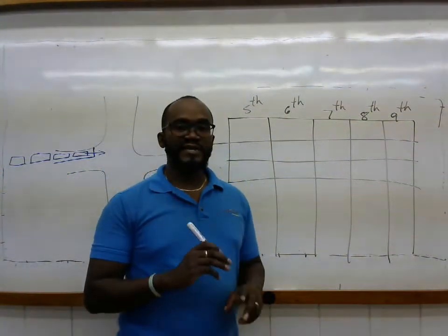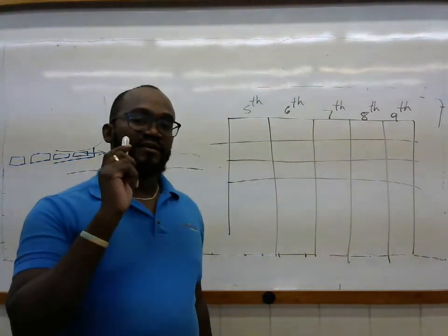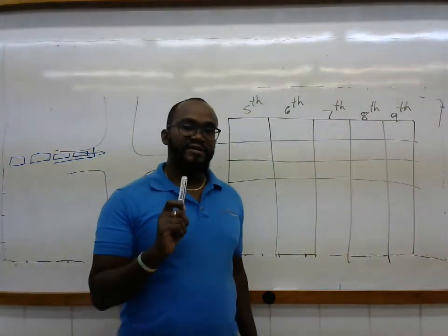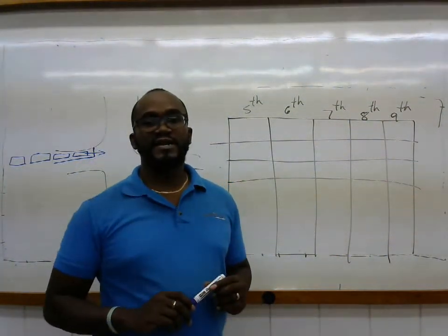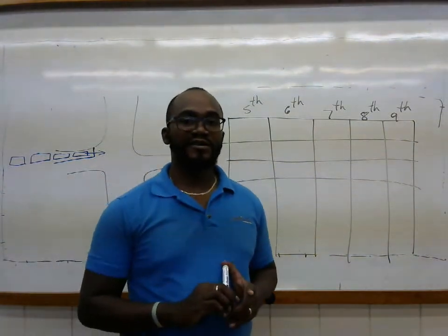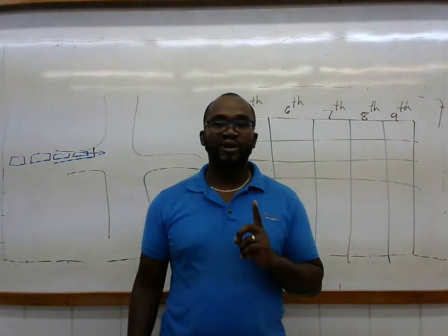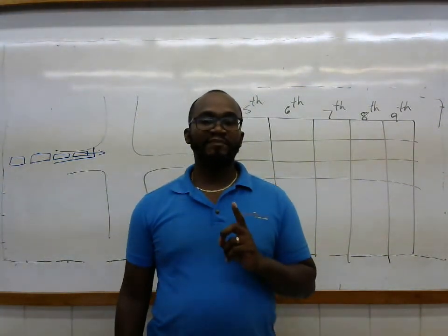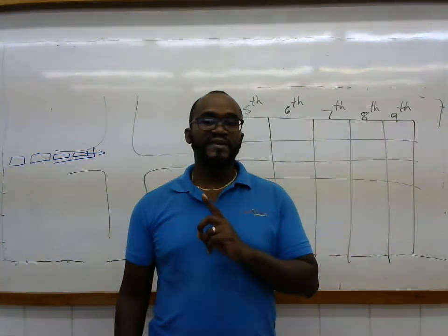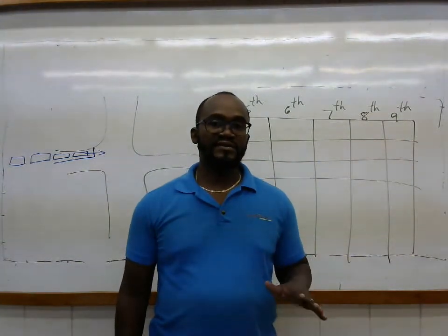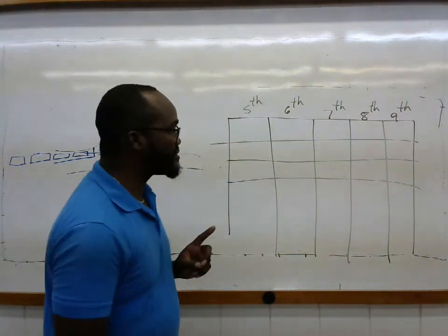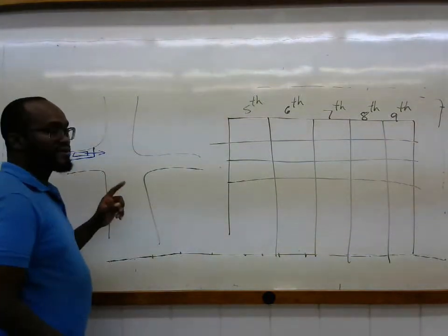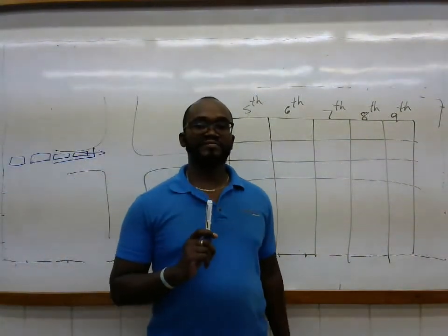Recall, saturation flow rate is, by definition, the maximum number of vehicles that can proceed through the intersection, assuming 1 hour of continuous green time. So the maximum number would also depend on whether the vehicles are moving at steady state or not. So we ought not to be measuring vehicles that are not moving at the cruising speed.